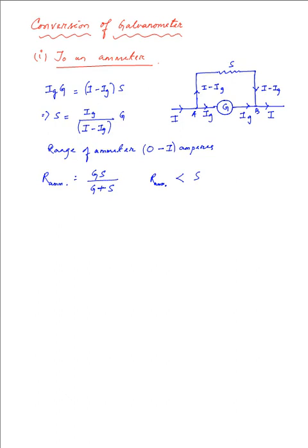So it has to be connected in series to the circuit, and as a result of the low resistance of the ammeter, we do not experience any marked fluctuations in the value of current. Now as we can see over here, the shunt has not only extended the current range, but it has also lowered the resistance of the ammeter.